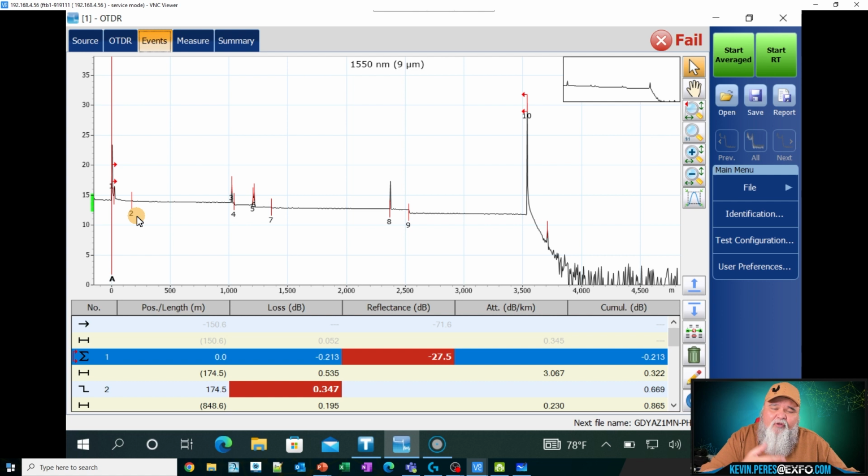But in this case here, I'm talking about the OTDR. If you have an in-service OTDR, you can test while there's still light on the fiber. So just disconnect from the receive card, plug it in, test through your site, and now you know which connector is giving us the most noise, right?